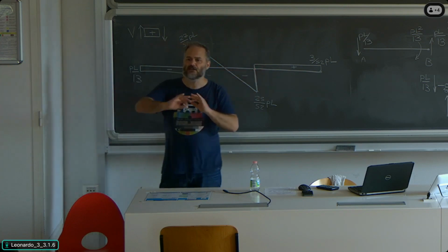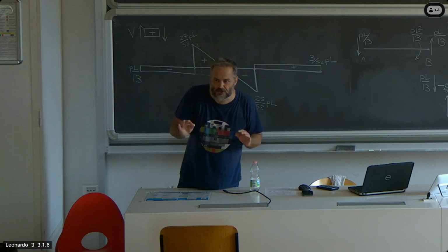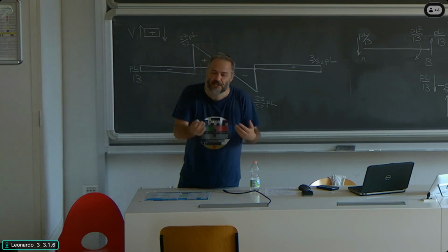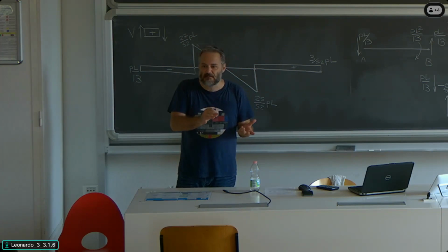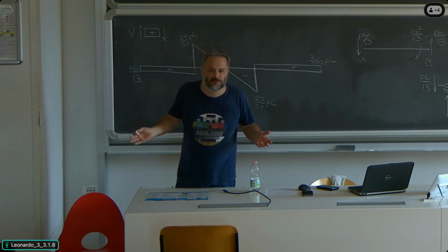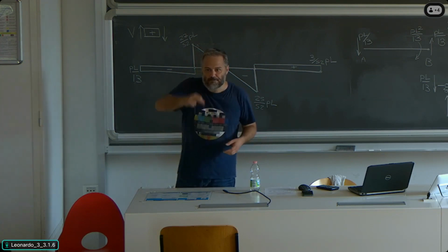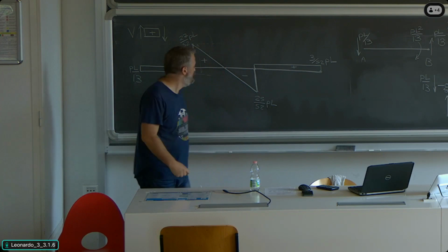Reaction forces are no different from concentrated loads. As a matter of fact, they are concentrated loads. So their effect is the same as we saw yesterday when you have a concentrated force in the middle of the beam. Okay? Jump in the shear force.